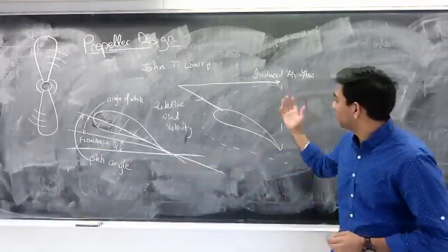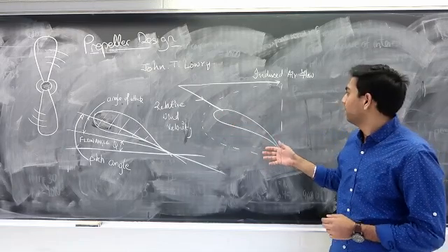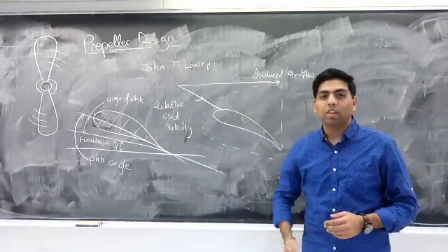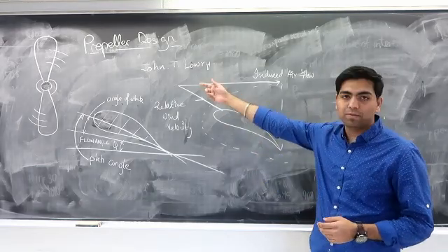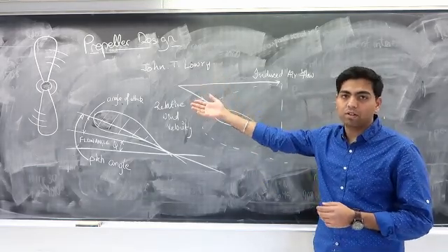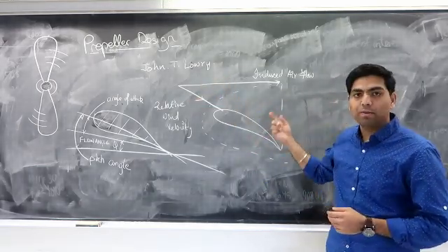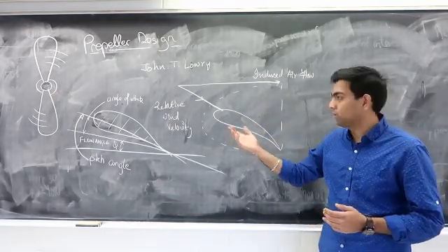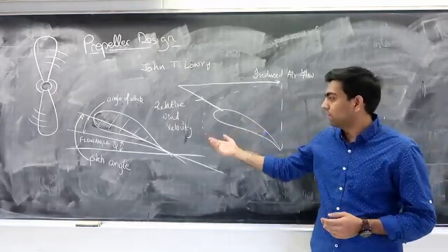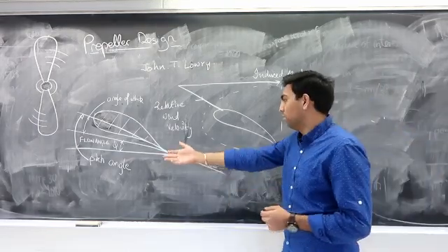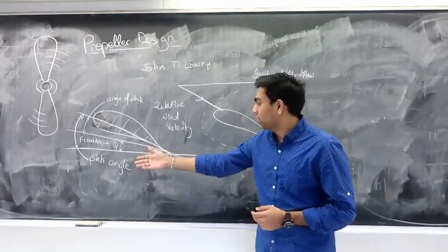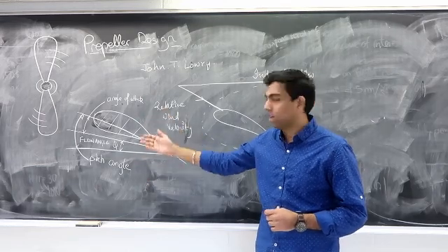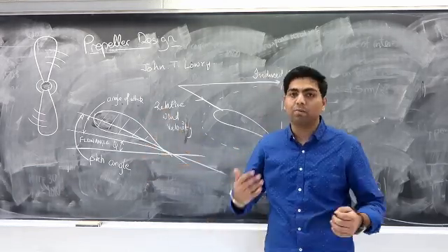Let's say this is the airfoil and this is the hub of the propeller, and you have the induced airflow, which is the true airspeed, the free stream velocity coming in front of you, and the speed with which the propeller is rotating. The induced airflow is the summation of the two, and that causes a relative wind velocity, which is explained better here. The pitch angle is basically a summation of the flow angle and your angle of attack. Your flow angle comes basically from a downwash.